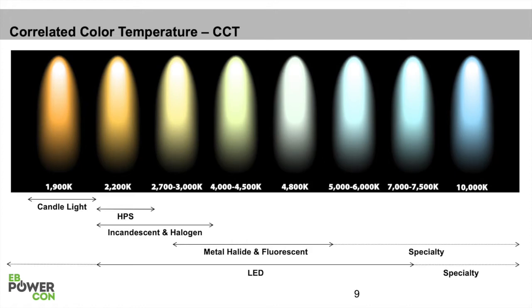It is the best kind of warm color temperature for trying not to disturb nature. Everything from bugs to birds to people. So it's something to think about. A lot of designers are looking at the more warm colors, so around 2,700, 3,000 Kelvin for outdoor lighting.